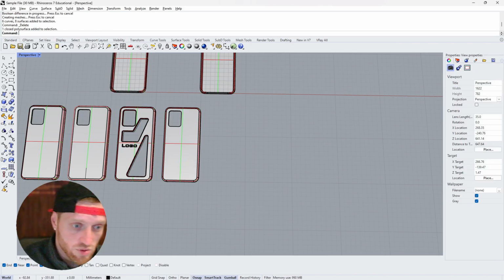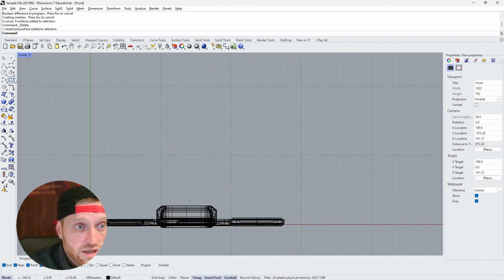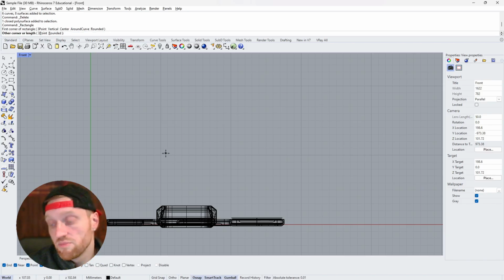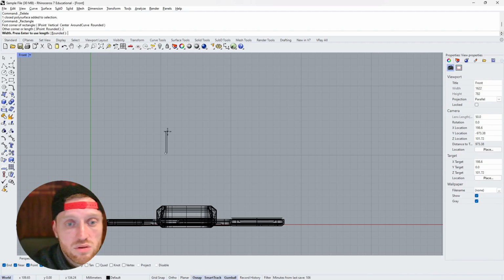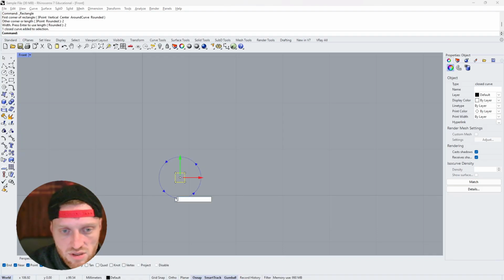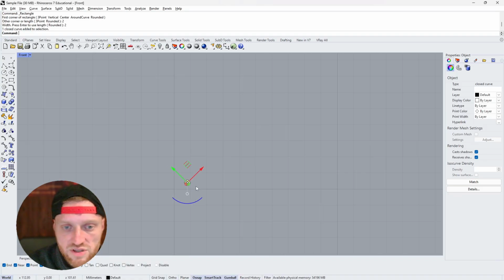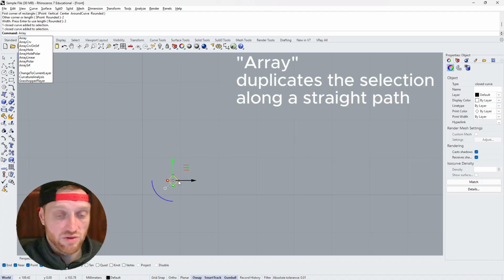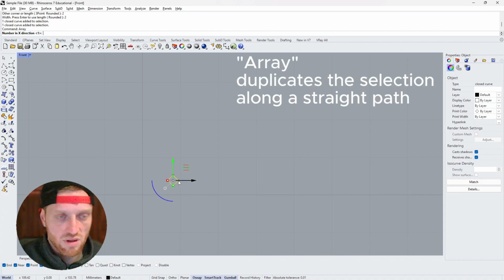Another option, I think, which is quite nice and simple. Let's say we take this guy. We click anywhere. We say 2 by 2. And now we have a square 2 millimeters by 2 millimeters. I click, say 45 degrees. And now I use the array command, right, to multiply. How many do I want? Let's say 15 copies in X, 1 copy in Y, 1 copy in Z.